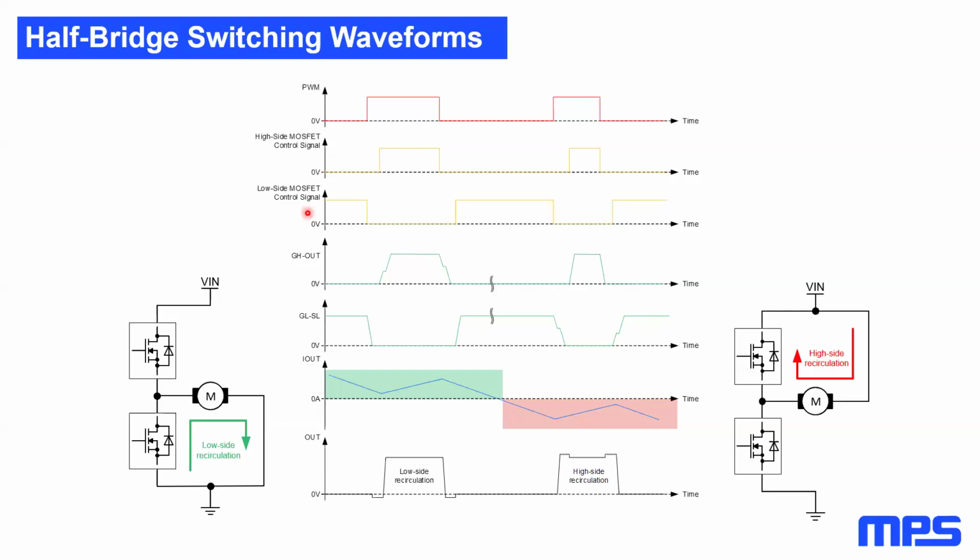Yeah. Okay, thanks a lot to both of you. The next one is why low side MOSFET switching losses is 0. I don't think that was the case. Can we go to the table? No, the body diode, we said the body diode in the high side is 0 in case of a low side recirculation. And the switching losses is 0 in the low side.